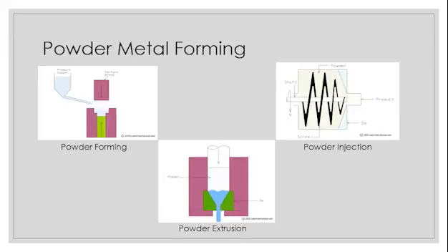The process is completed in three steps. The preform is heated so that binding can be easily done. Pre-alloy powder is put into the die and pressed by the preform. In this process, we get 80 to 85% solid density, and after pressing by the preform, it again goes for mechanical pressing, so that we can increase the density up to 98% or 99.5%.